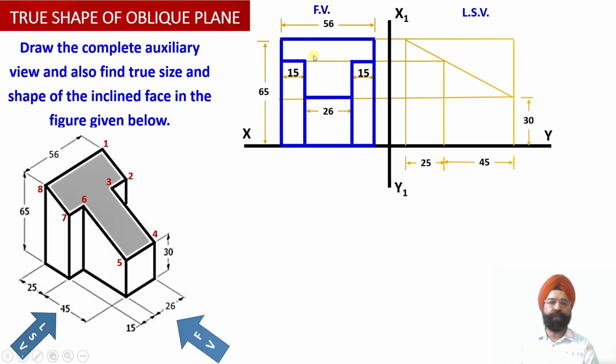So now we can observe that this is the T section, which is an inclined cut section which has been cut by an auxiliary face at the top of the solid. Now we can check, this is quite a big surface over here. So this bigger surface appears to be a relatively much smaller projection onto the front view.